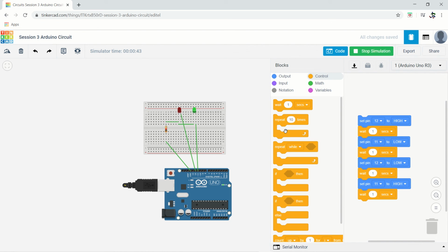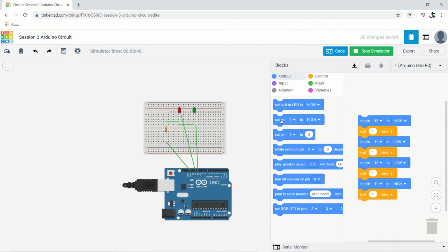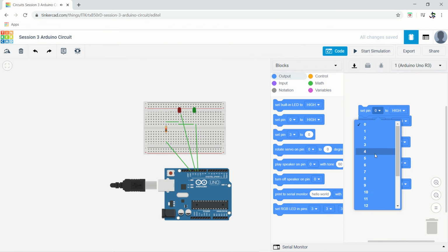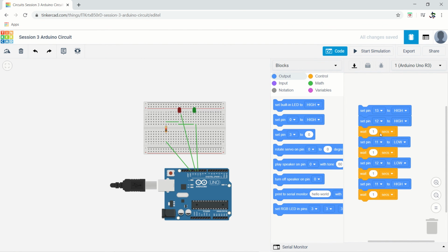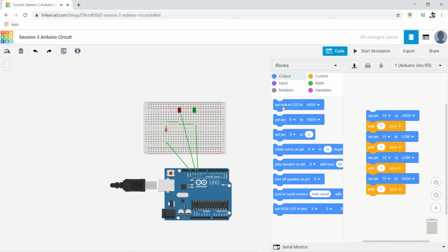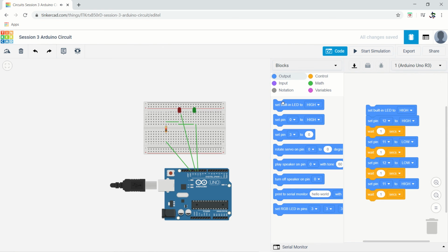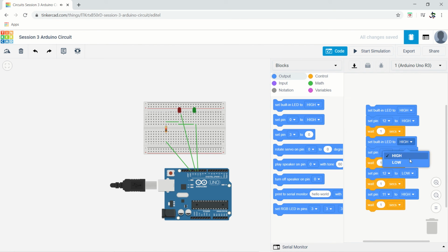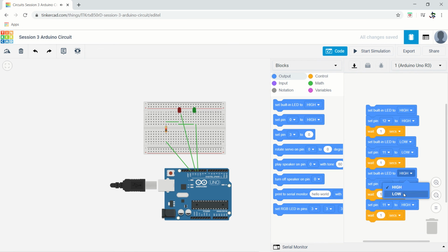If you want to do the programming of 3 LEDs, you have to add one more pin. Suppose I am using the inbuilt 13 now. The inbuilt one has a specific command, so we'll use that specific command for the inbuilt LED. So here high, here low, if you want low, then here you want again high. So let's do high, then low, then here you can do the low. Okay, then simulate it again.